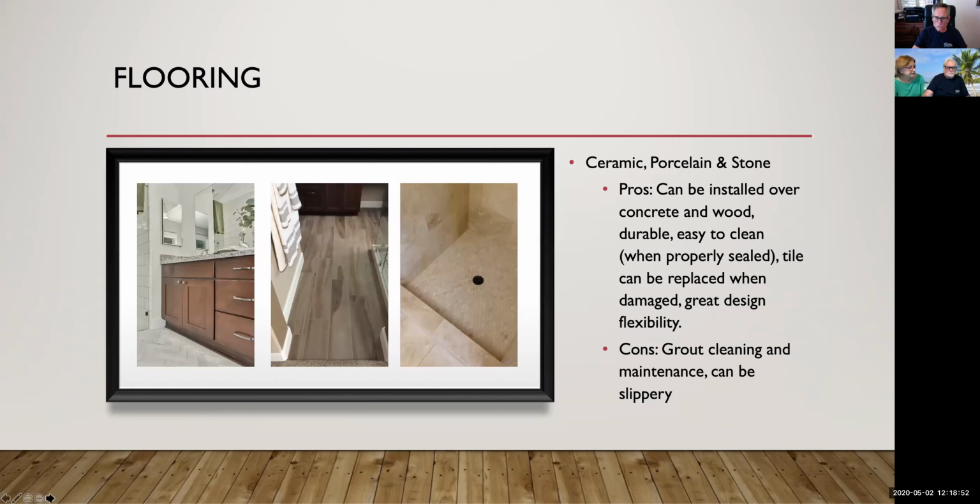So a little tip for you: when you're looking for a bathroom floor, take a bottle of water to the tile store with you, pour a little on your finger, rub it over the tile. If it feels like you're ice skating, put it down and walk away. Go find something else with a little more slip resistance.